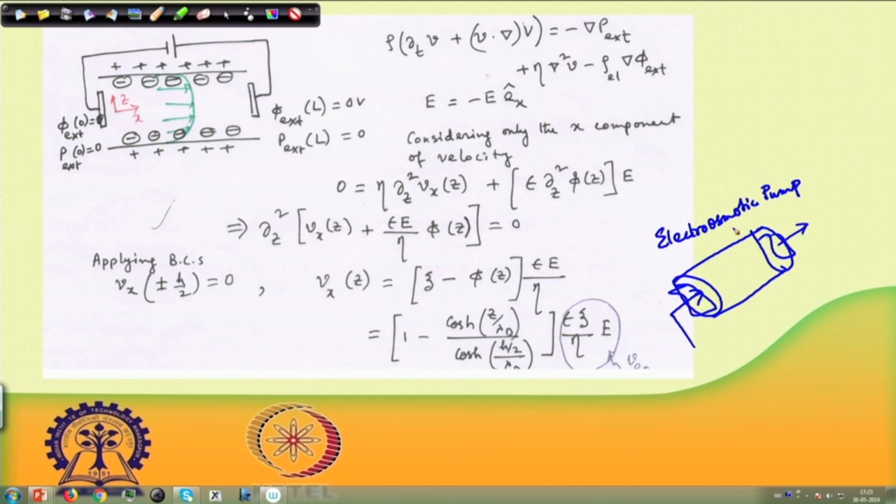Even in a microfluidic sense, there would be piezo operated pumps, or a similar mechanism in place even if there is not an impeller, but that needs a huge amount of investment in terms of micro electromechanical systems. But here, by a simple channel filled with glass beads and by applying a voltage, one can create a pumping action where the fluid will flow. This is known as electro-osmotic pump, and for this a porous medium is used to create this kind of a channel.